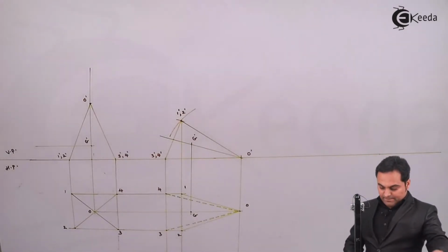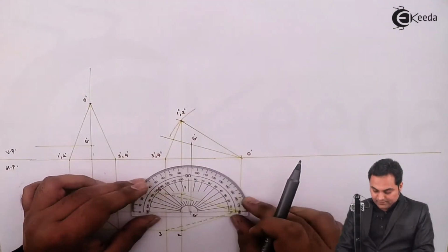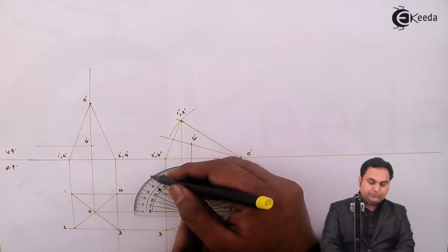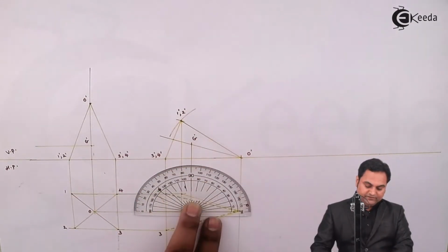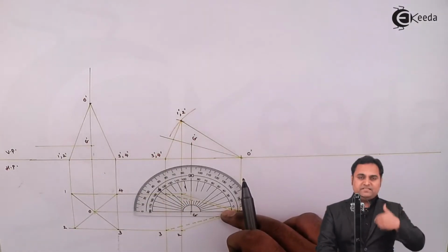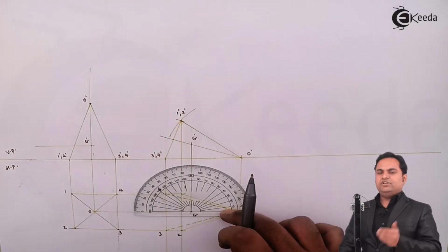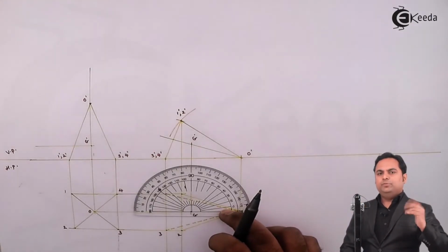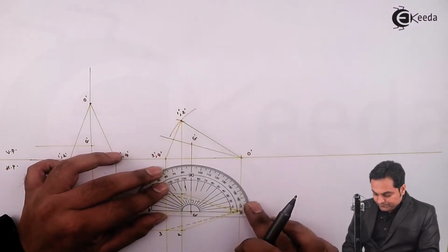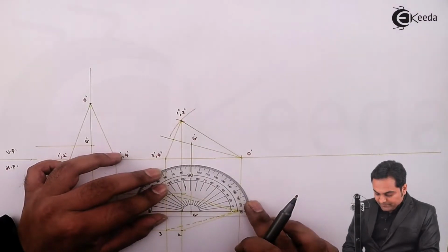So if I am measuring 30°, then instead of taking 30° from the left, because if I take from the left, in that case the cutting plane will be passing in such a way that apex is retained, but here in the question they have mentioned that apex should be removed, so I have to take 30° from the other side, removing the apex.